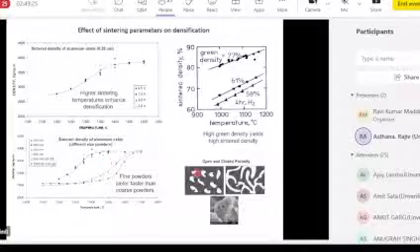And even after sintering is done, you have parts with a certain amount of porosity. Porosity could be open porosity or closed porosity. When you have open pores, they are usually interconnected and they can be impregnated or infiltrated with another metal. So if you have a stainless steel part with interconnected pores, you can impregnate that part with molten copper. Copper will seep or wick through the pores, and once this solidifies, you get a fully dense part.